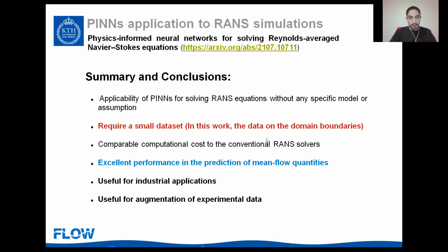And we saw that the computational cost is relatively comparable with the conventional RANS solvers. Also the performance of the model can be much better than the conventional RANS solutions. So we think that it's very useful for industrial applications, and also when it's needed to augment experimental data and have a continuous solution from sparse measurements, these kinds of simulations could be very useful.